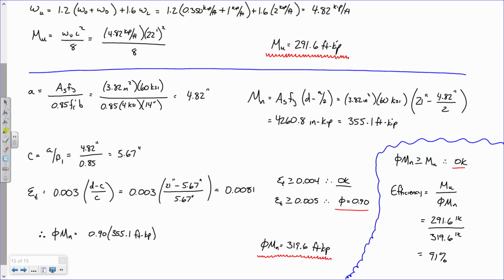Move on. Yes. Hold on. One quick question and we're good. So let's say I do one full iteration of this where I get my efficiency factor and I do this in Excel. Can I go back and say, okay, let's make this 1 by changing B and automatically go ahead and... We're going to talk about that on Friday, and we're going to talk about what parameters will actually affect it the most. You'll be surprised, if you double f'c, it doesn't change it that much. f'c actually isn't that big of a deal.